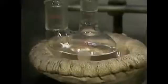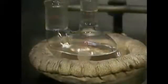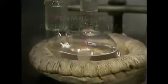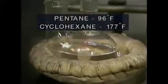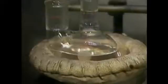The liquid mixture we'll use consists of 50% pentane and 50% cyclohexane. These components have boiling points that are relatively far apart. At atmospheric pressure, the boiling point of pentane is approximately 96 degrees Fahrenheit, and the boiling point of cyclohexane is approximately 177 degrees Fahrenheit. In this example, the pentane is the lighter component. Its boiling point is lower than that of cyclohexane. The cyclohexane is the heavier component, and it has a higher boiling point.